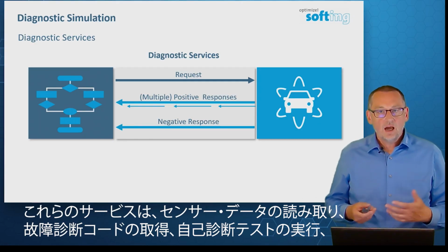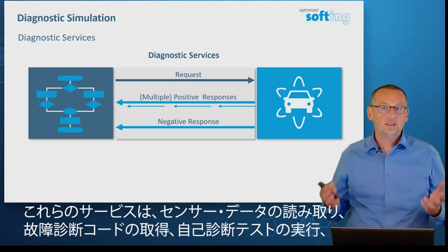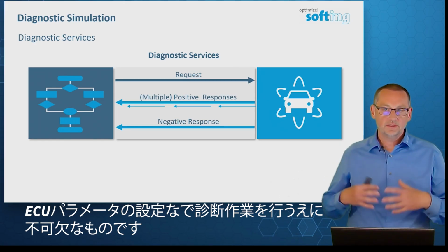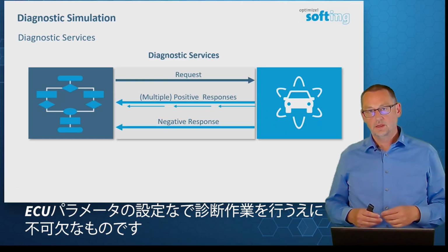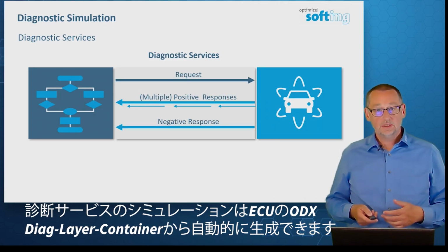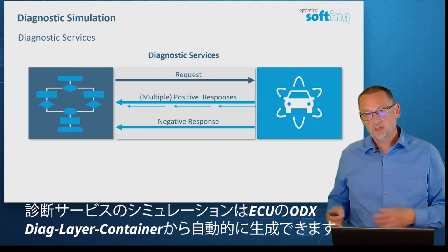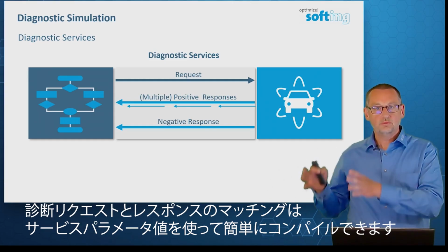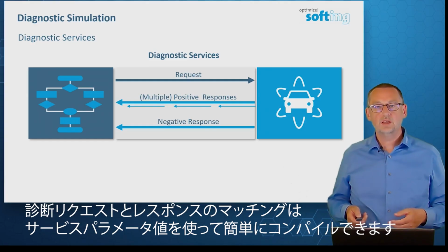These services are essential for conducting diagnostic operations, such as reading sensor data, retrieving diagnostic trouble codes, executing self-tests, and configuring ECU parameters. The simulation for the diagnostic services can be automatically generated from the ECU's ODX diag layer container. Matching pairs of diagnostic requests and responses can easily be compiled using service parameter values.